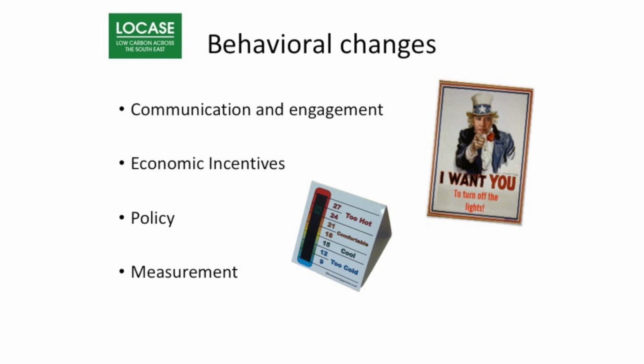So, for example, you know that in June the energy was way too high. Why was that? It could be because you had the aircon on, but it could be that you left equipment on for no reason. Successful monitoring and targeting can achieve 5 to 25% savings according to the Carbon Trust, and the payback time is instant.